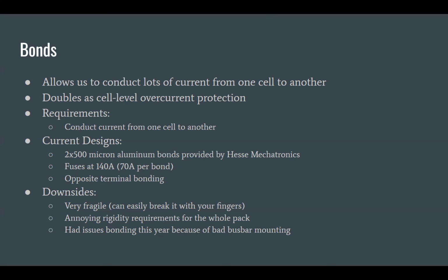While that's not great, generally nickel strips can handle something in the range of 10 to, if you're lucky, 20 amps. So we would still be able to output up to, what would that be? Assuming that we're trying to draw them all the same cells, that would be 80 amps at 600 volts. Yeah, well, it'll fuse before the bonds would, because it'll be rated to a lower.